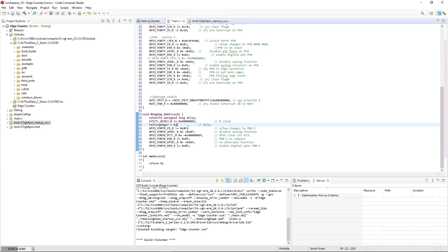So that's done. Then we went ahead and did the commit changes register. You don't actually have to do this for port B, but we wanted to. In this case, I have my LEDs connected to pins 0 through 3, and I just wanted to demonstrate that you can make changes to every pin at once on each of these ports. So like this says, I want to make sure all my following changes to pins 0 through 3 are allowed, set them all not to have analog function, set them all to P control equals 0, set them all to outputs so the dir is 1, and turn off their alternate function and enable them to be digital.